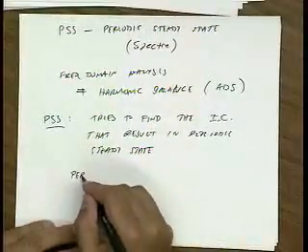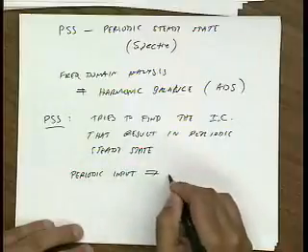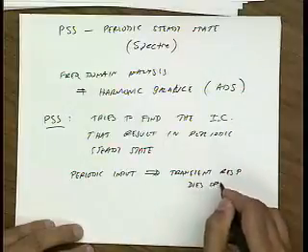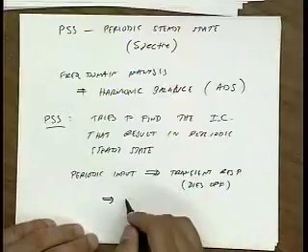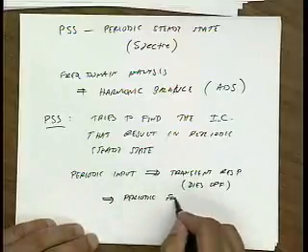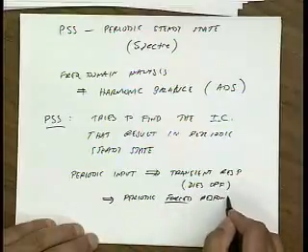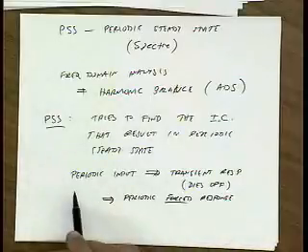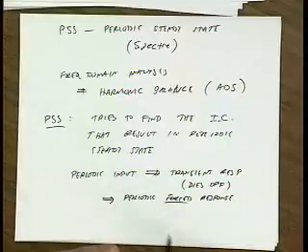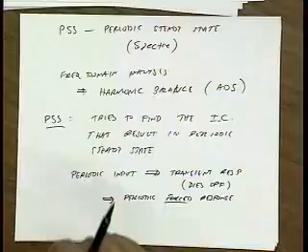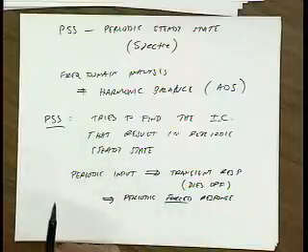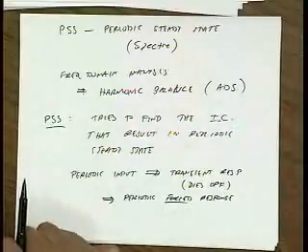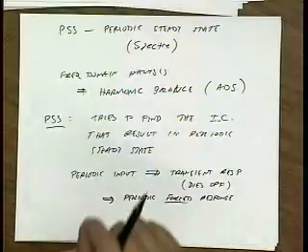So I have a periodic input. Then I get a transient response, and it dies off. And then finally I get my periodic response, what we call the forced response, which is at the same frequency as the input, or its harmonics, right? So the idea of PSS is, instead of running a long transient to get to this state, what if I could find the initial conditions in steady state? Then all I have to do is simulate one cycle, and I know the complete behavior of my system because it's periodic. So the trick is to find those initial conditions.